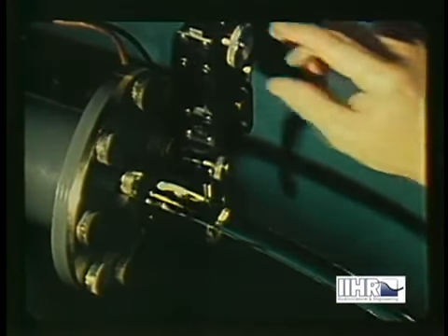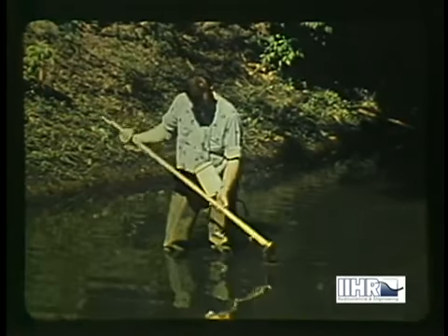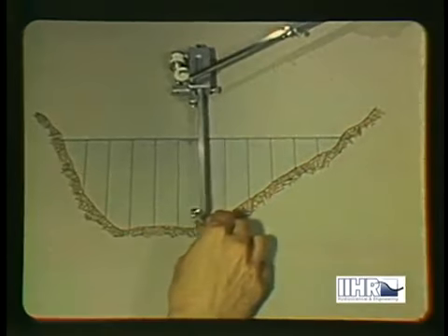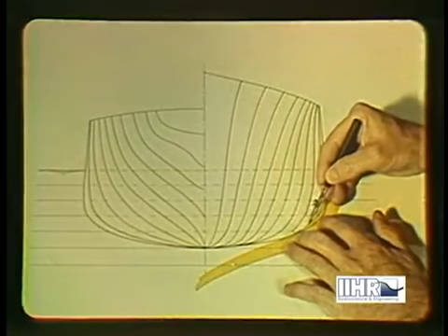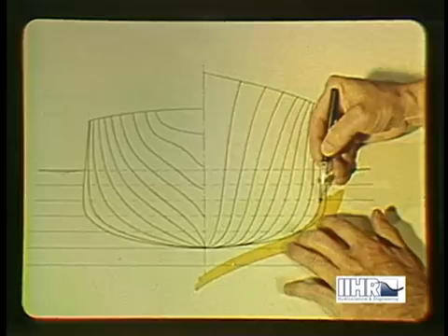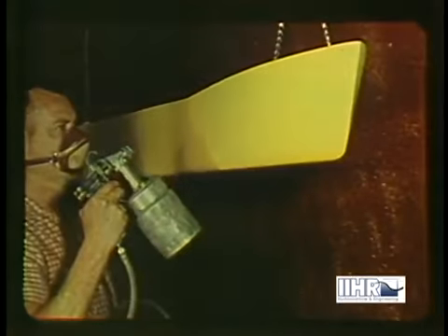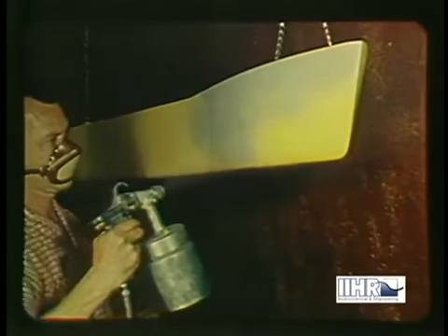The shape of a fluid stream can be described in terms of length alone, whether one measures the diameter of a jet with a micrometer or the depth of a river with a staff. The principle is the same. The area of the flow passage is then determined by planimeter in terms of length squared, and the volume is length cubed. The same procedure is used to define the form of a ship hull, whether a prototype or a model such as this. Scale is a very important factor in fluid mechanics, for the size of a boundary is as important as its shape.